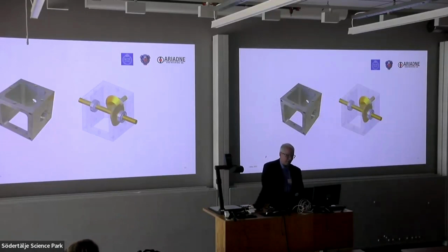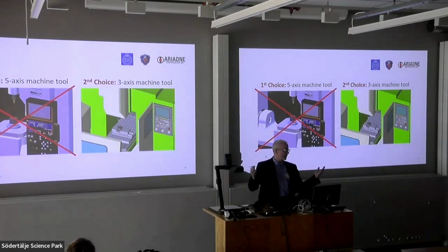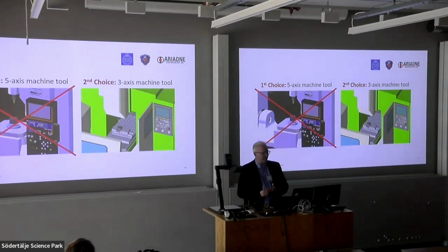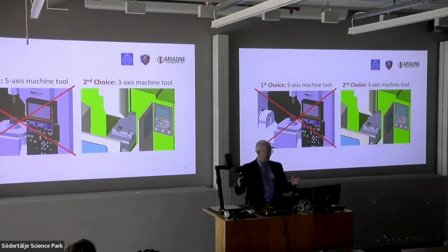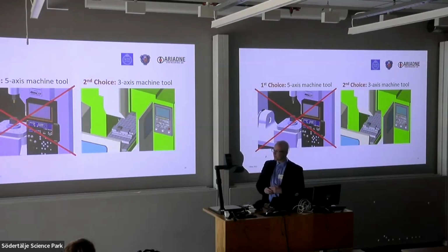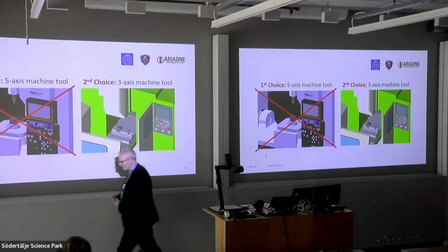And I think that all of you know a lot about manufacturing. I think you would say that, yes, of course, if I have a 5-axis machine, let's do it in a 5-axis machine, because then it's just a matter of the machine accuracy. Unfortunately, in this case, this machine was broken, so we had to do it in a 3-axis machine, meaning that we have to split it up in several setups. So now we have a tolerance chain. And Miroslav will present that case, how we're using your software to evaluate if the process plan will end up in the right product or not. So please.